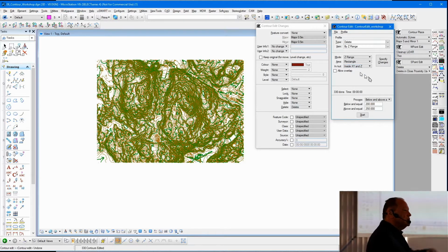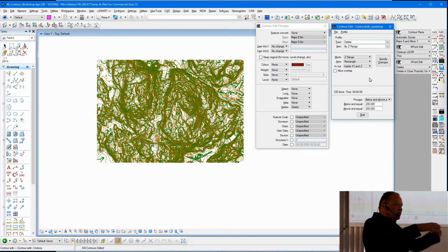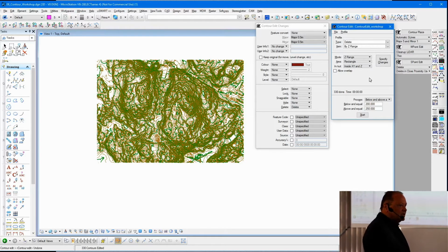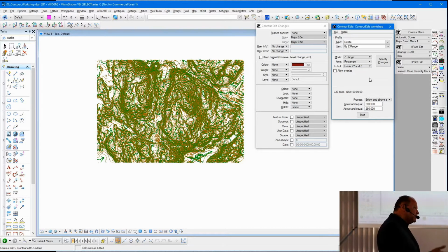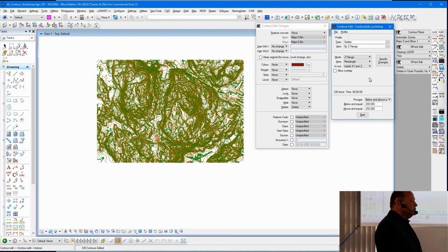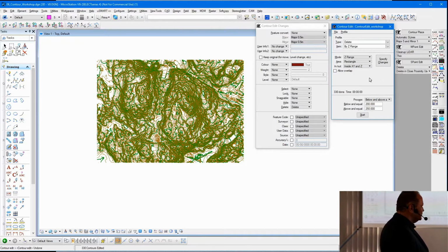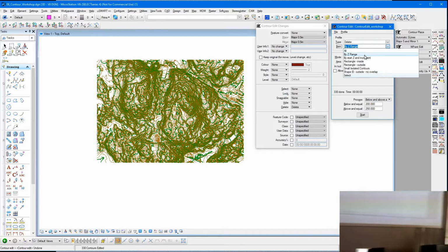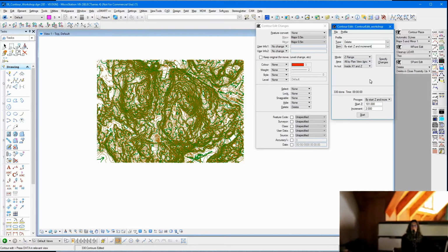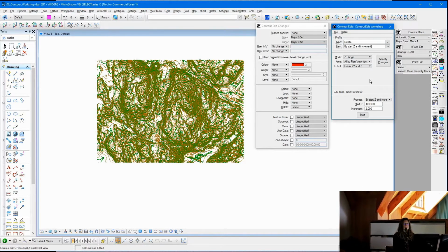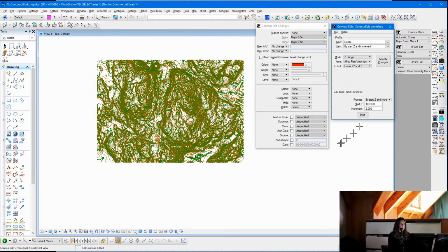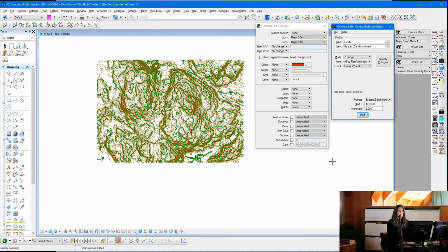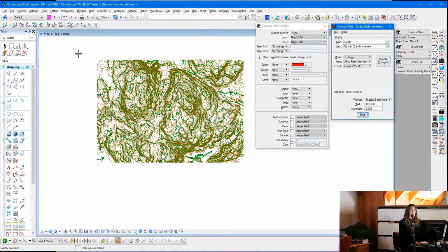Let's say all the contours are wrong. Something went wrong above a certain height. Now we can fix them and recontour those ones. And you've gone to a lot of trouble. You've labeled all the other contours and everything, and you've got all the tools now to do it. So we also added by start and Z increment, which was a request. So I'm going to delete all the odd numbered contours now. Right, so we'll only be left over with all the even ones.